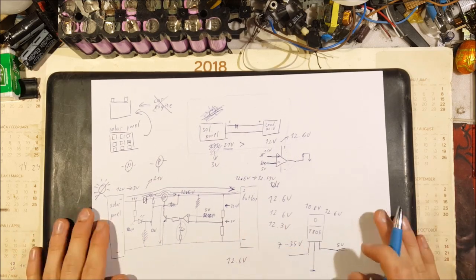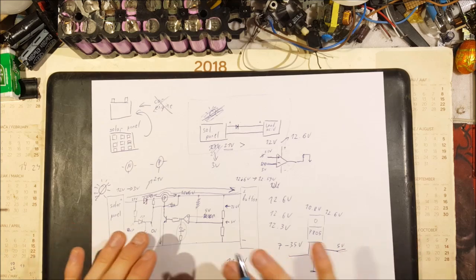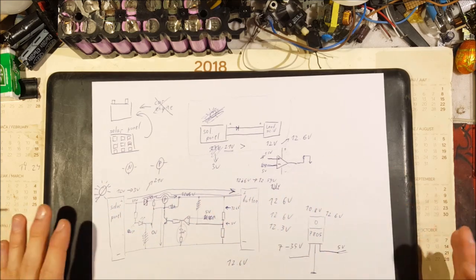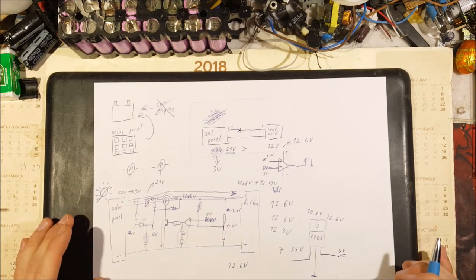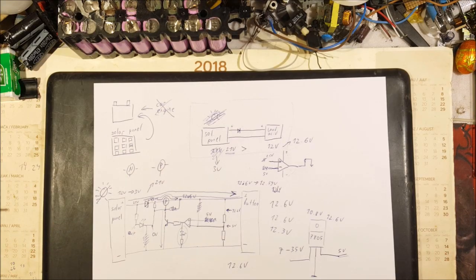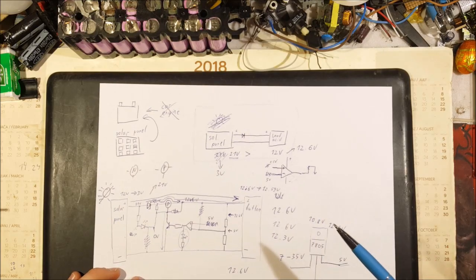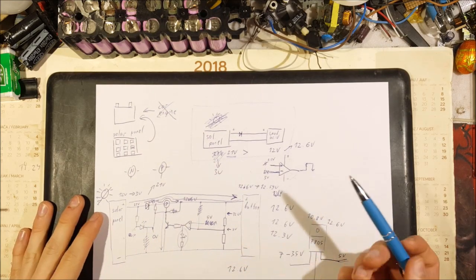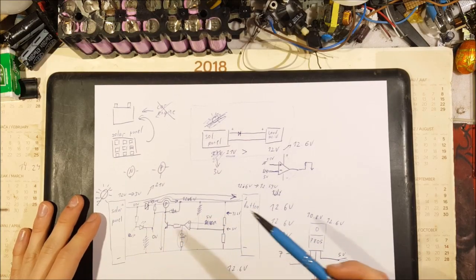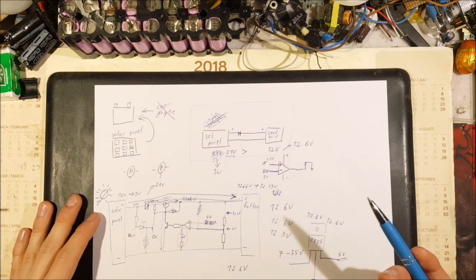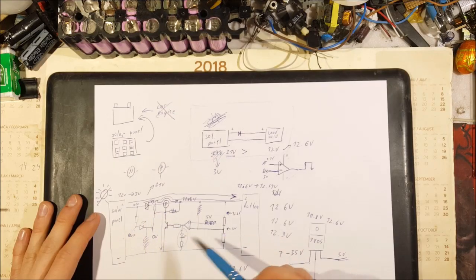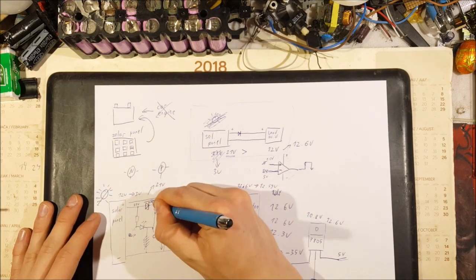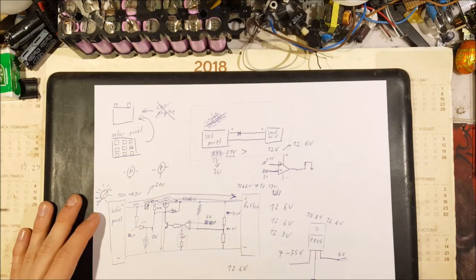And that's pretty much it. That is our entire charging circuit of questionable solar system. Now we just need to add few values. This P-channel MOSFET, you can use any P-channel MOSFET as long as it can handle enough current. This resistor right here, you can use, say, 10 kilo ohms.